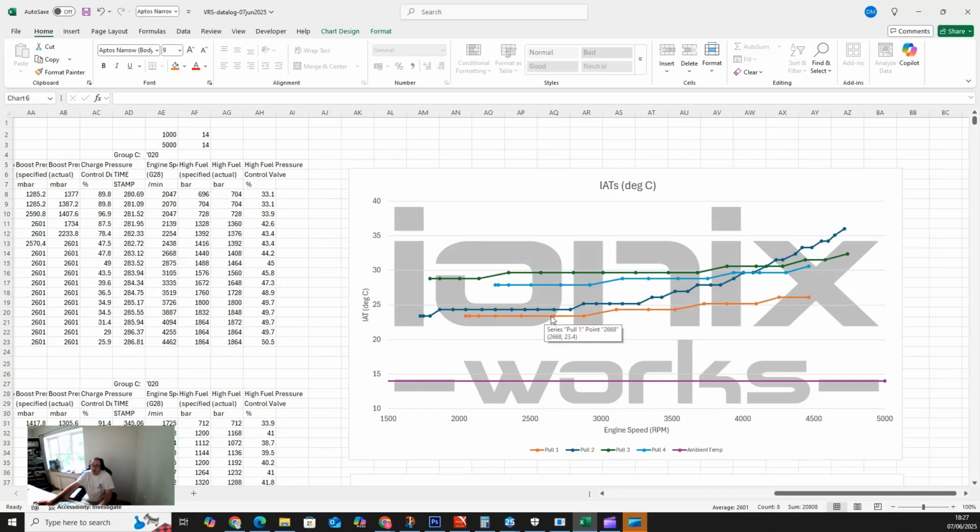If you're on a track setup and you're leaning on it continuously, you probably will start to see the system heat soak. In those applications, obviously, your requirement for modifications is different. So I'm looking at this from if I'm doing a spirited drive, am I going to see problems? You're letting the system cool back down before you go into another run. In the real world, am I going to see any issues here? And the answer is no.